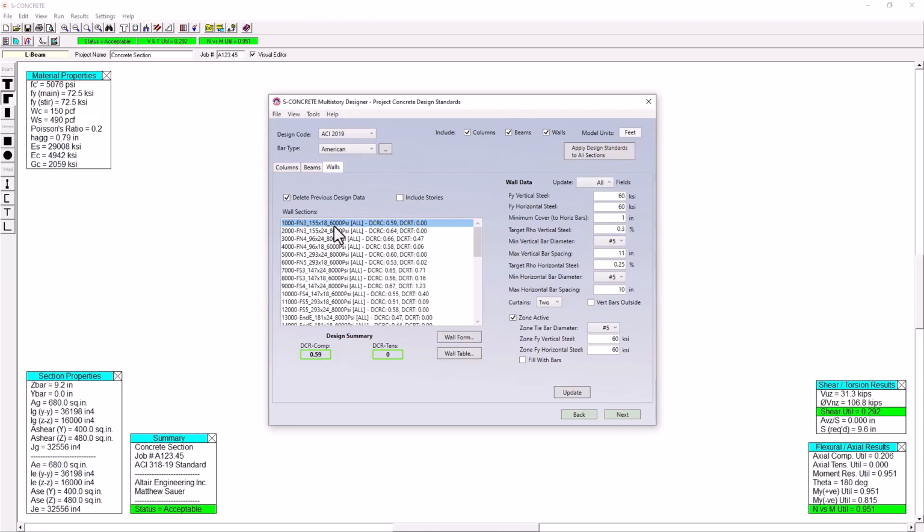And these parameters control which members go into specific design groups, essentially SCO files, and are checked based off of the properties in ETABS. Now we can also see here, we have in square brackets the word all. This just indicates that basically anywhere where this wall section is located, or this pier label is located, anywhere on any floor, we're going to consolidate all those locations and take the worst case loads from each one of those for design checks. There may be situations where we don't want that, in which case we can actually include story-specific groups as well.